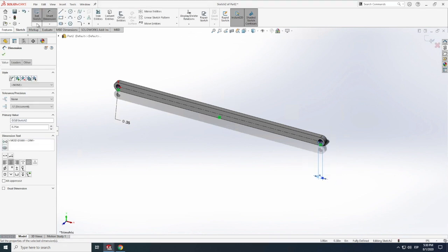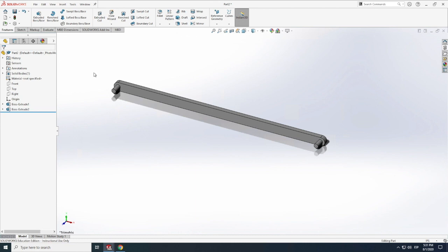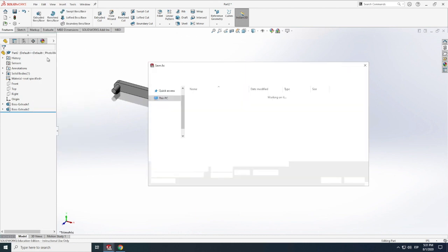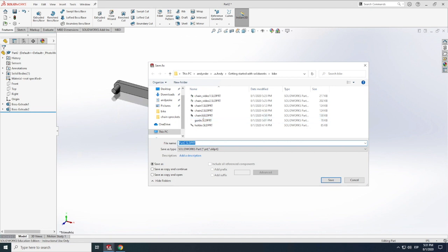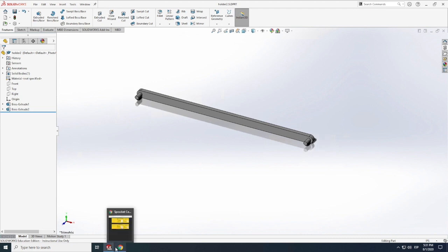And now when we're gonna extrude them, we'll just extrude them in 2 directions. So we'll make one direction be 0.5, that's what we want, and then in the other direction we'll just make it be, so it would cover that area that we initially extruded. And I'll save this as, as you can see I already have a holder from my previous practice, so I'll call this holder number 2. All right, then, so we have that.